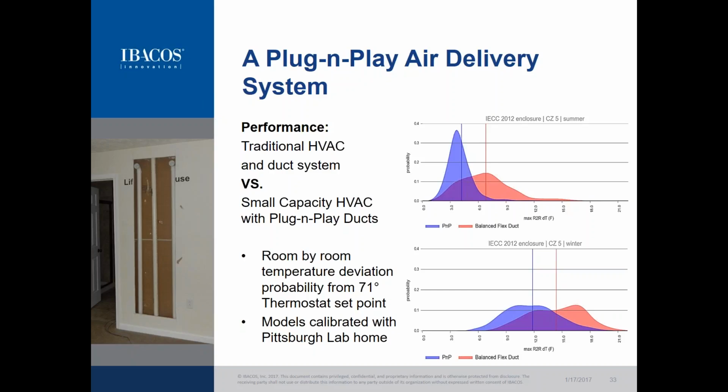So we saw less deviation from the T-stat, and the temperature deviation was a lot smaller with the plug-and-play than the flex duct system. So we're getting higher confidence levels of maintaining comfort in a smaller temperature band with the plug-and-play small diameter plastic system.